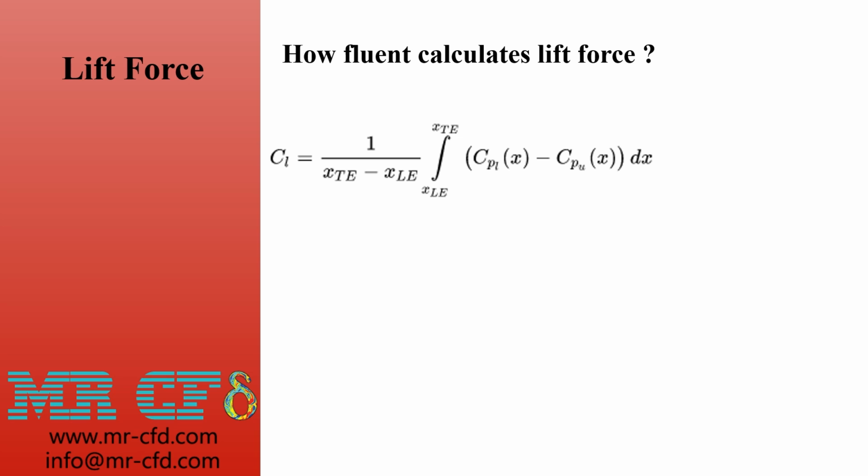And as you see, the expression is not suitable for direct numerical integration using the panel method of lift approximation. The panel method is the way we did it in the past, like in the early 70s, by using simple source flows like sinks, sources and vortices to model and approximately estimate the value of the lift. But now, with CFD methods, we can exactly calculate the value of the lift around the wing itself.